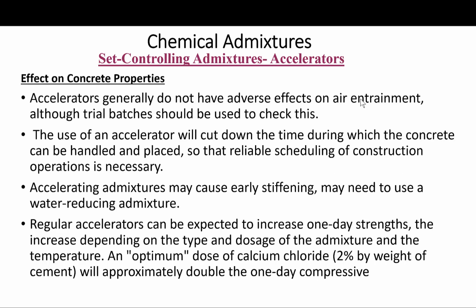So let's look at how these set controlling admixtures really affect the concrete properties. As we said, every admixture, whatever it is, air entraining, water reducing, set retarding, set accelerating, all these have effects on concrete and it should be investigated. But from what we know, accelerators do not, as a rule, have adverse effect on air entrainment, although trial batches should be used to check this. Again, we go back to trial batches.